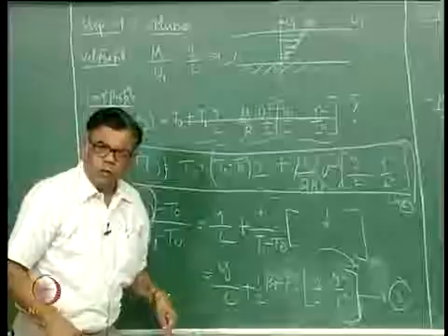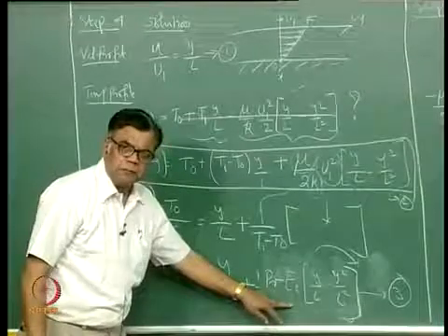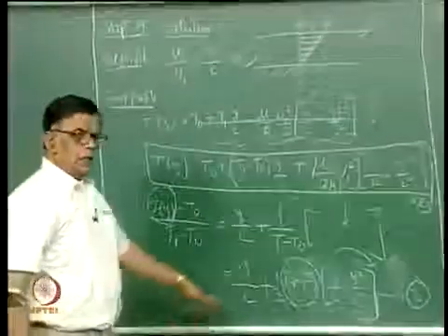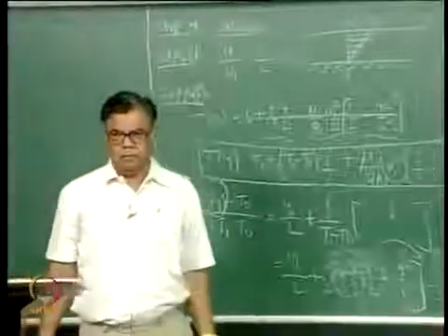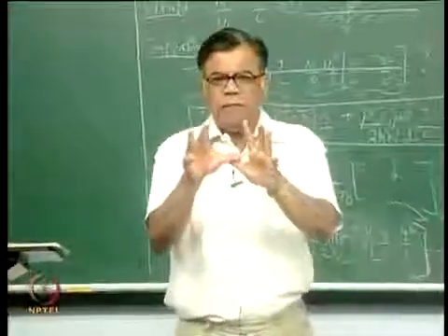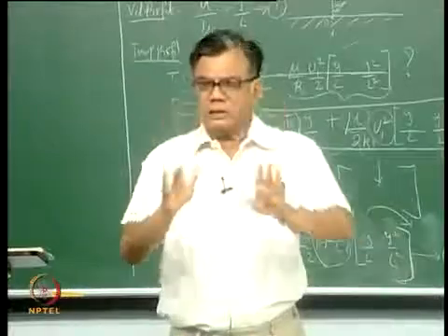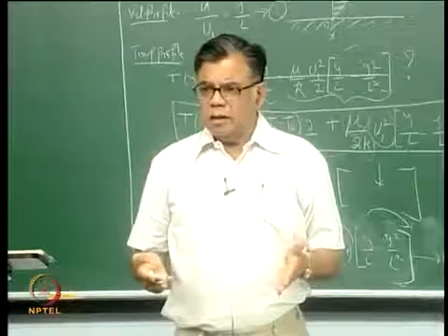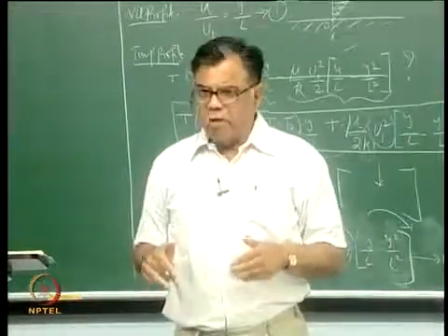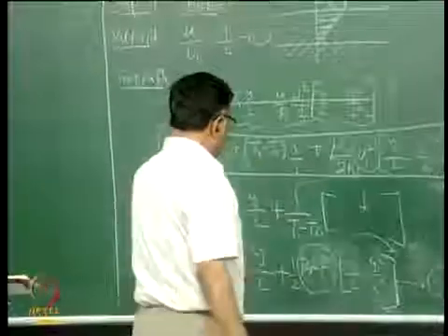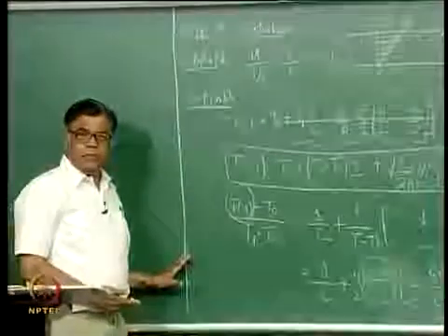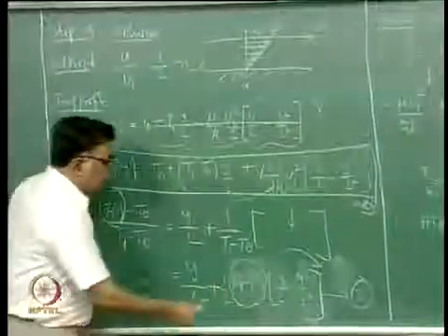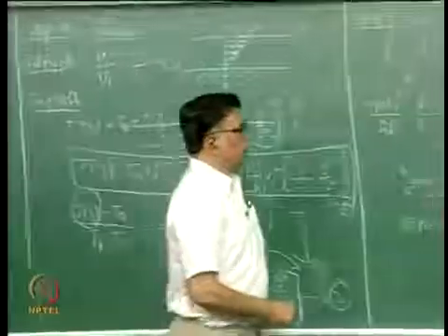The moment I bring in u1, that means Eckert is coming into picture. Tell me, give me the effect of Prandtl-Eckert number. That will give the effect of the u1, more importantly viscous dissipation. What numbers can it take? Huh? You do not know, you can assume now at this point in time. I am going to suggest to you, use this expression. Now this is a very nice non-dimensional expression, it came off just like that. Plot y by L and this for various Prandtl-Eckert numbers.